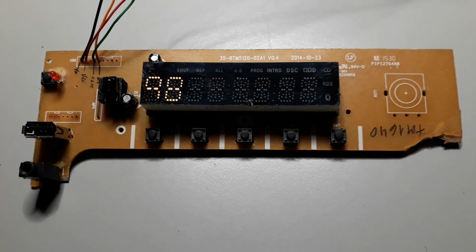In this usage example, to write digit 8 of the display, we need to write to the memory registers hexadecimal CE and CF. Each digit uses 2 bytes to reach the 16 segments.